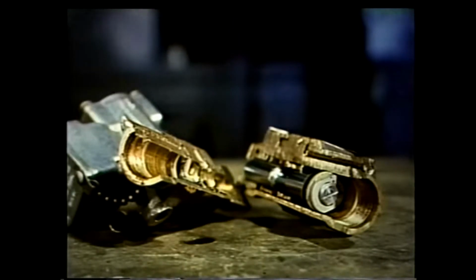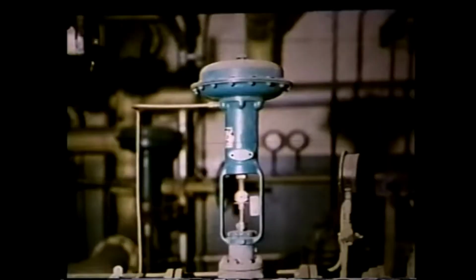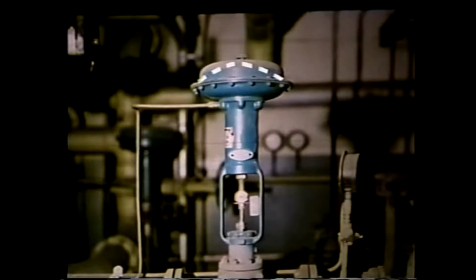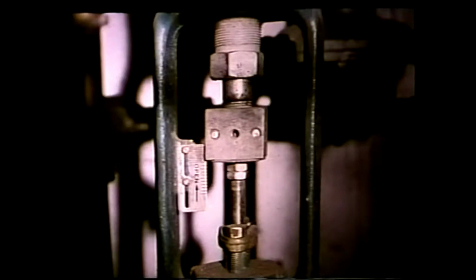Electric solenoid valves are usually used to control the flow of air to the valve. They're either fully opened or closed and are not used for throttling. The diaphragm operator is run by air or hydraulic oil pressure. Varying the applied air pressure of the system causes the diaphragm to move. The diaphragm is attached to the stem, and as it moves, the stem also is moved and the valve opens.